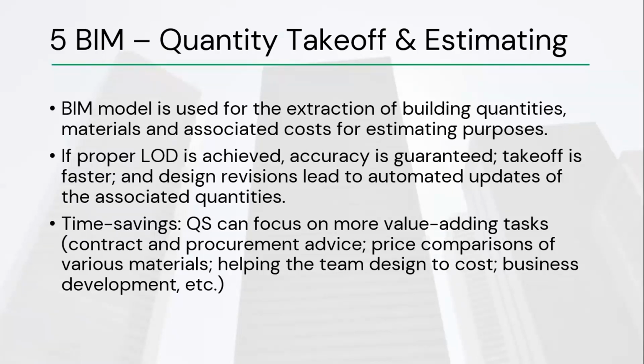And even in the early stages of the project, we'll have information that we can use to advise the client and the project team on costings. So it also reduces time used when doing manual takeoffs and allows the estimator to focus more on value-adding activities. This could be stuff like contract and procurement advice, price comparisons of various materials, helping the team design to cost instead of waiting for the team to complete the design and then costing the design.